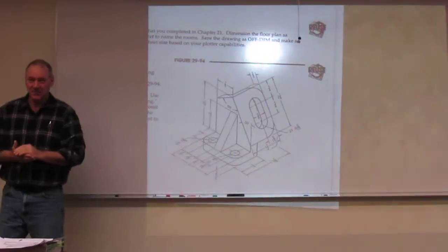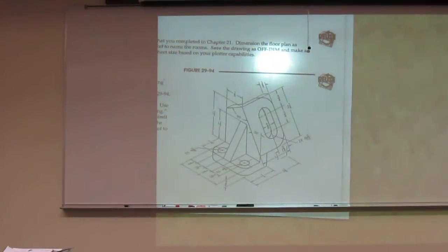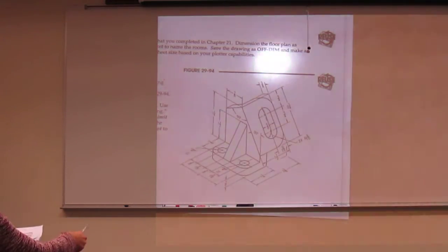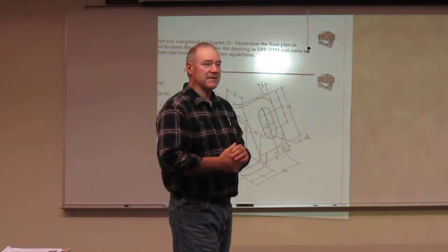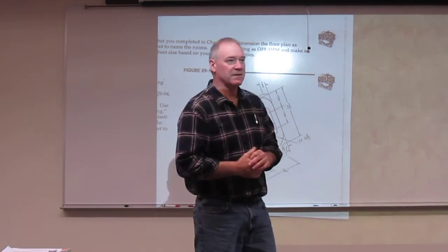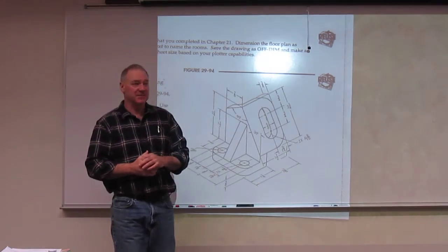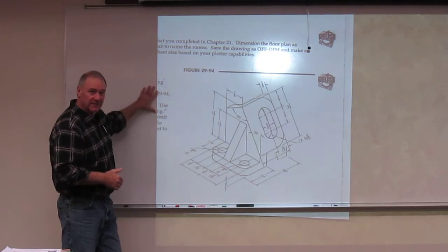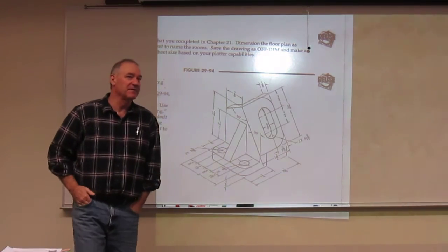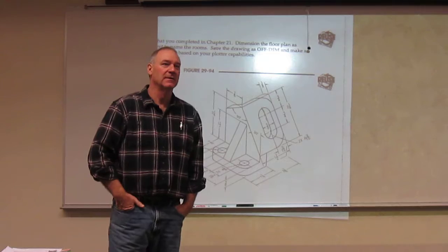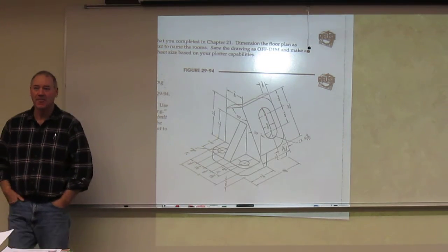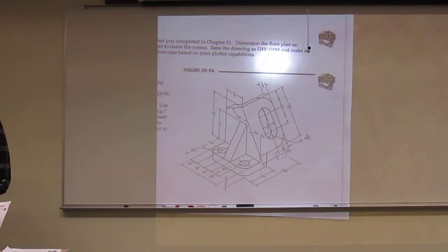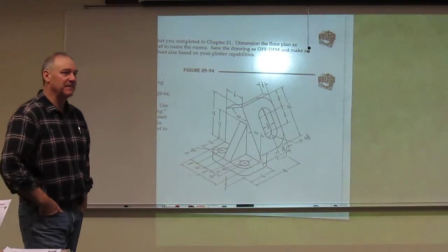Now, where are the discrepancies on this? First off, the instructions of the problem versus the instructions on your sheet. So in essence, on this, they give you fractional format, but they ask you to switch it to decimal, and that's all right over here. And how many decimal places do they ask you to go to? 3. Go to 3. Okay. Except for one area. And the slot goes 4. Right? And they want you to use limit dimensioning.